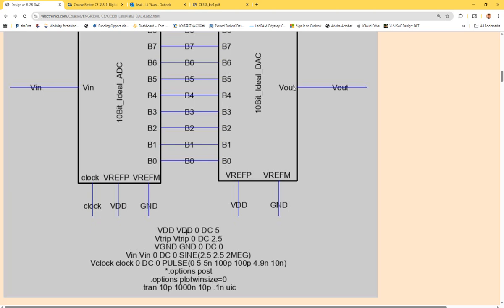That's the voltage drop of this sine wave voltage. And that's the DC 0, which is the DC offset of 0 volts. So there's no DC offset being added to the sine wave. And then it's followed by the amplitude of the sine wave, which is 2.5 volts. I'm thinking that it's not doing anything here, but it's actually adding an offset in this sine wave function for some reason.